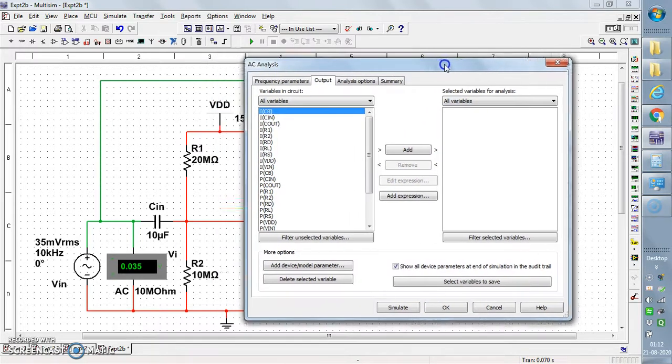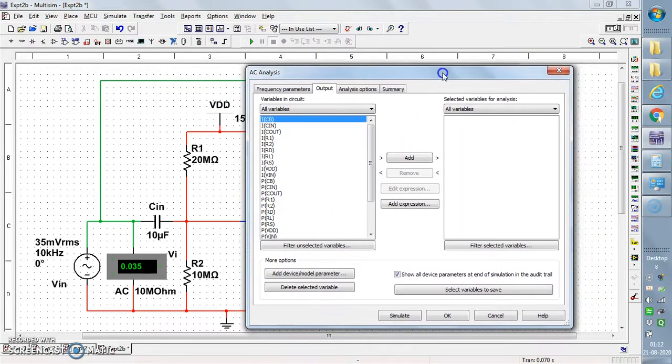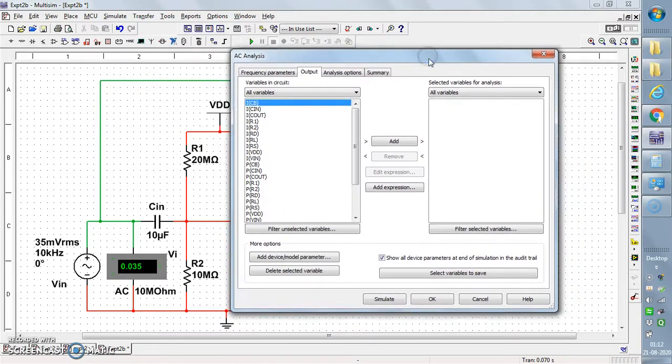Now, considering that the frequency response curve is nothing but a curve which gives us the details about how the voltage gain of an amplifier varies with respect to variations in the value of input signal frequency. That is what the frequency response curve is. So voltage gain is nothing but a ratio of output voltage by input voltage. Let us design the equation. Output voltage.